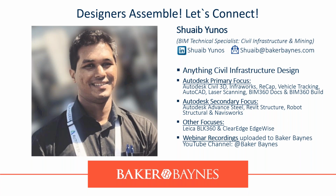Another question is how to link a Civil 3D finished surface to InfraWorks. If you've got an SQLite file that has been generated, as you've seen, I started it with InfraWorks just to create more of a collaborative approach. Once you import the SQLite file into Civil 3D and you've created your final network surface and you link it back to InfraWorks, all you're going to do is relink that updated surface and it will update in InfraWorks. Simple as that. There are a lot of cool videos on YouTube that show it. You can check it out.